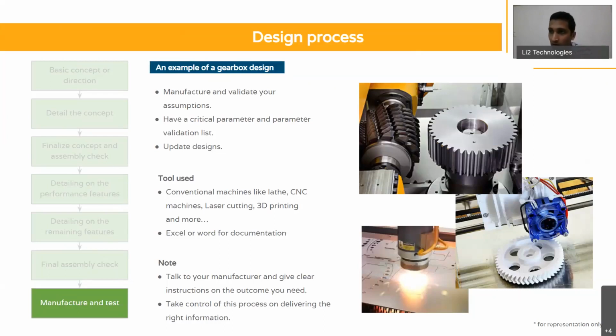So during your concept stage and during your design phase, you can always talk to the manufacturer, understand what they have and what kind of instructions they need, and make sure your design caters to those instructions. This is something that happened to me even during the gearbox design, which I was part of. We made sure that we spoke to the manufacturer to understand the kind of tolerances that he can achieve and made that available in the drawing. It is extremely important that we take this phase seriously, and don't take it lightly.